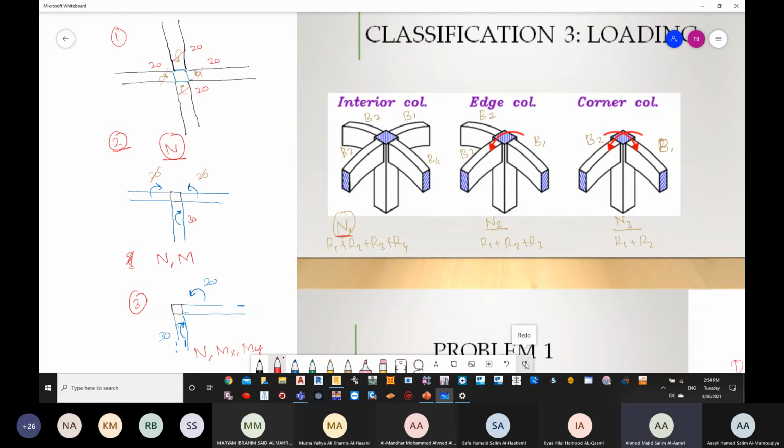So in short, we have 3 scenarios. Scenario number one, where we are only designing for loading. If we are designing for loading, we call this one axially loaded. Second scenario, if we design for one moment, either mx, if mx is there, then my is 0, or mx is 0 and my is there.